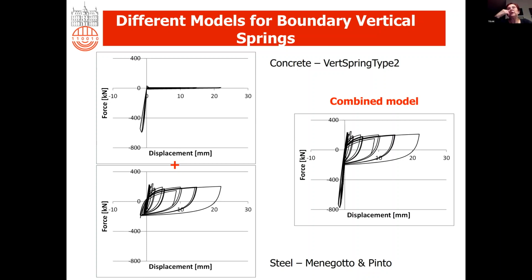I mean, the use of only this material. We added the Menegotto-Pinto steel model to represent the response of steel, and we coupled these two materials to obtain the actual response which was observed in the experiment.